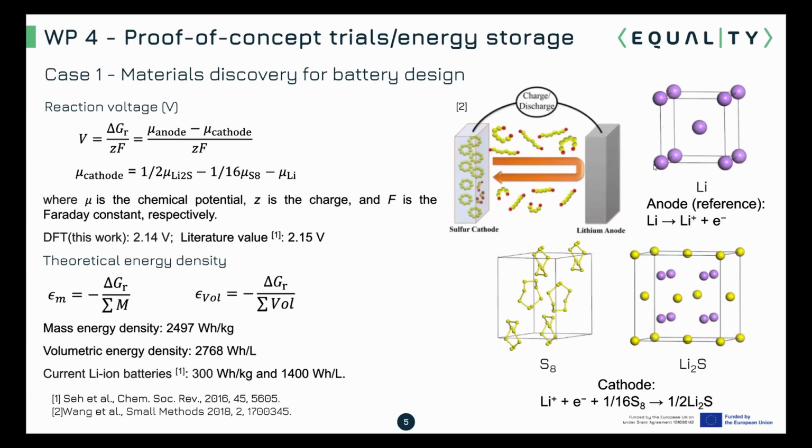Here is again a sketch of the working principle of such a battery. Here you have the sulfur cathode, the lithium anode, and this sulfur cathode is at the beginning, before discharge, completely made out of sulfur. This is present in the state of such sulfur rings, ring-shaped molecules. And finally, it's transformed to lithium Li2S, which is a bulk crystalline material in ideality.